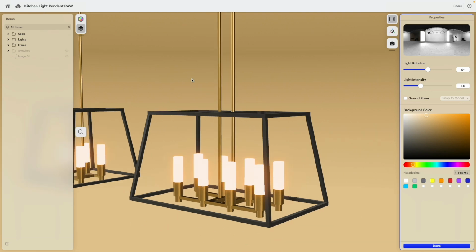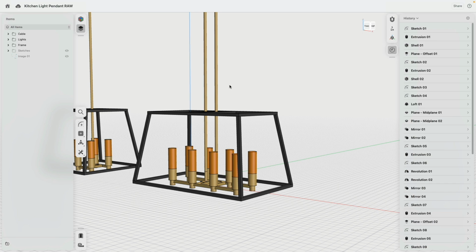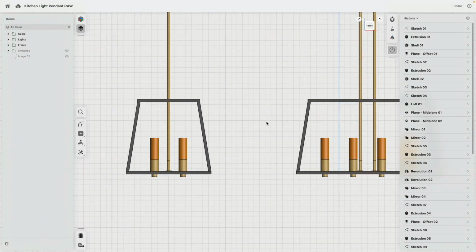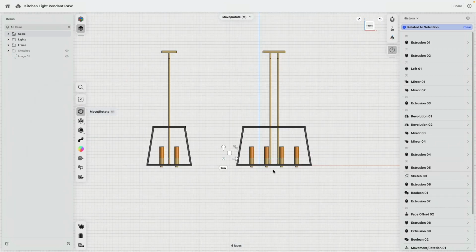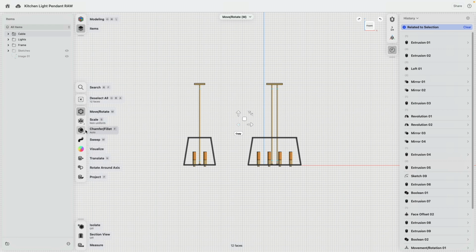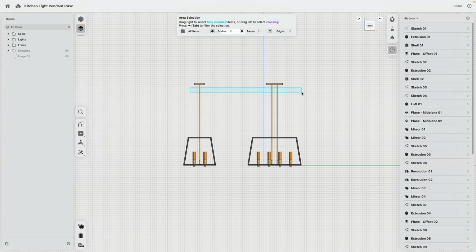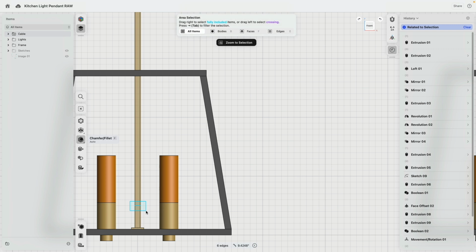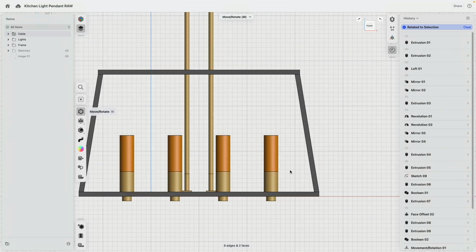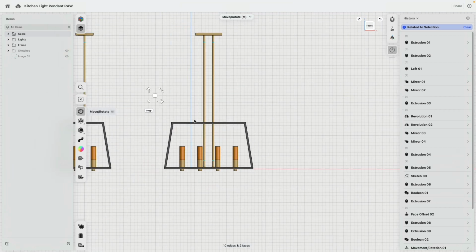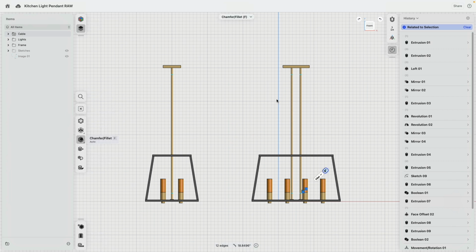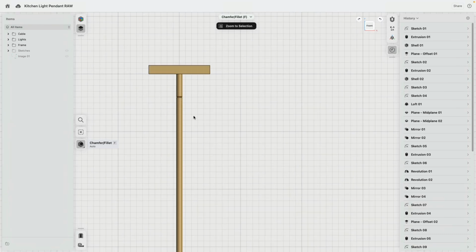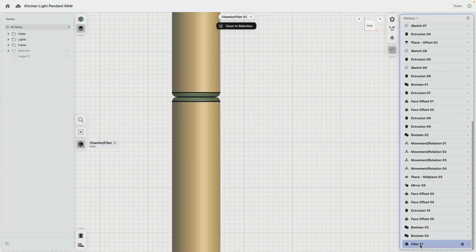Edges aren't really rounded. This is not something that necessarily has to be done because this is more like a really quick concept model, but the edges which I will round are actually those, because there I would select edges. I would like to add a small fillet. And let's say 0.0 here, chamfer fillet 0.05. Let's see. Oh, that's maybe a little bit too big.